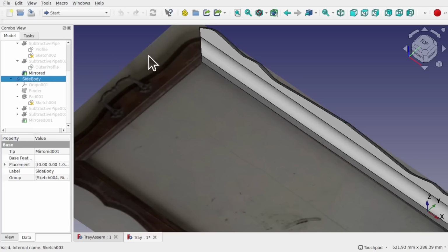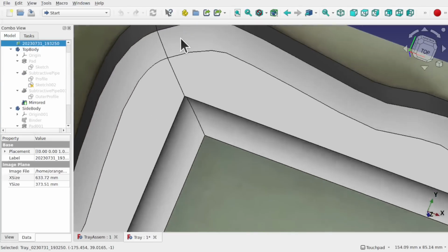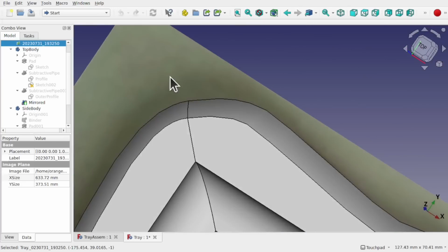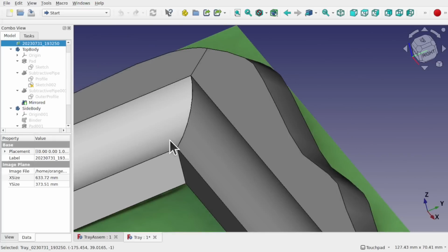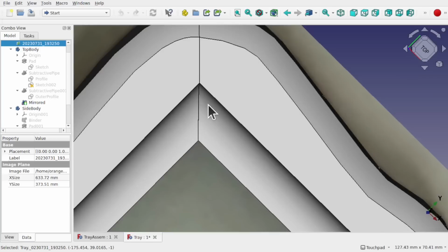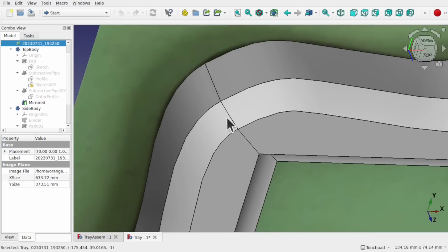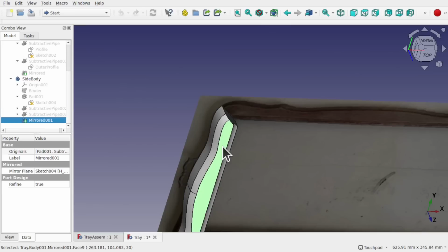So I'm looking at the top and the side. So we've got two bodies in there, and you can see how we've got tangency going across this bevel, and these can be any shaped bevel. As you can see, I've got a concave bevel in here, or they could be something a bit more elaborate. And the idea is to keep this tangency, because this is a B-spline going around here, and we need to keep the tangency across those because these are two separate parts.